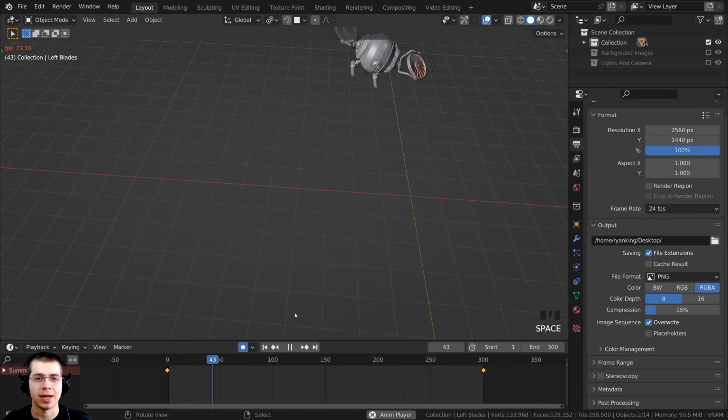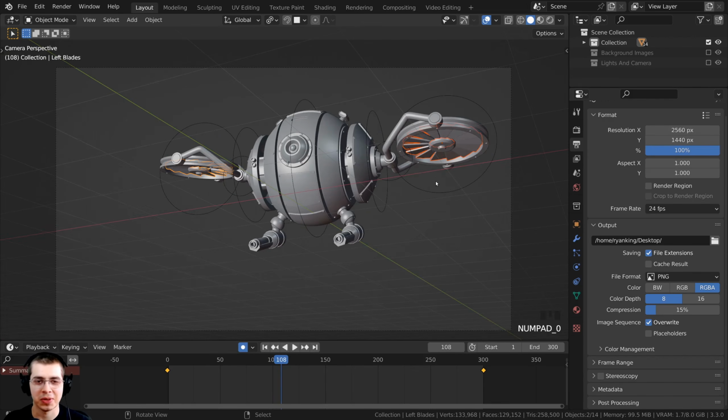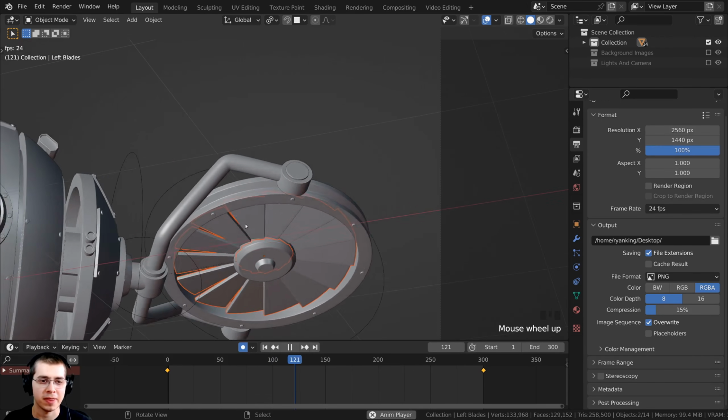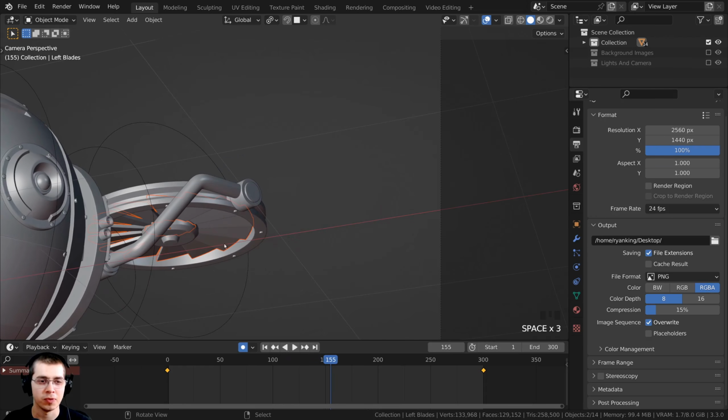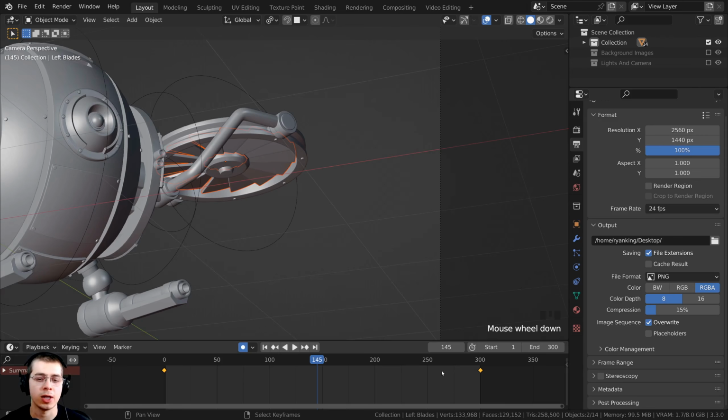They're going to be playing at a consistent speed, so that is looking good. Now actually if you look right up here at the rotor blade and play this, it looks like it's hardly moving, and that's just because it's moving around so fast that it almost appears as though it's not rotating. There is going to be motion blur when we render this, so that will help, but we can also just move the very end keyframe here to make it look like it's moving around more.